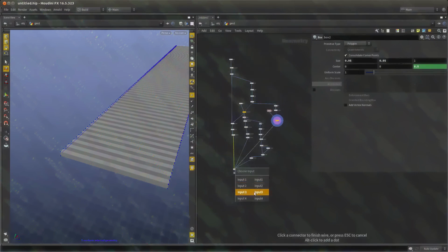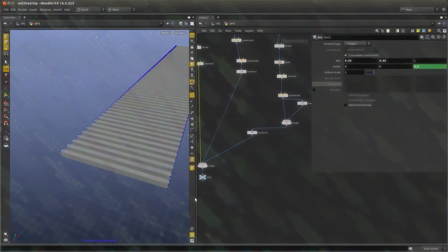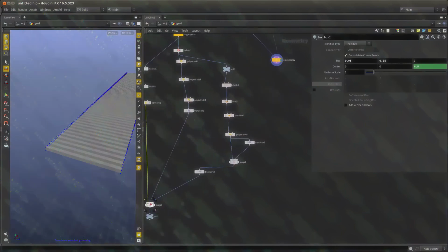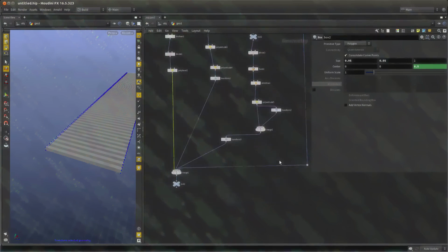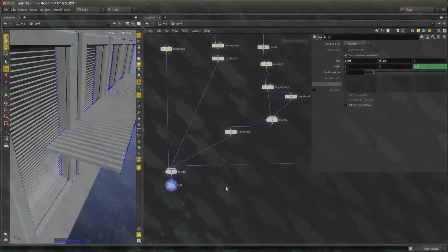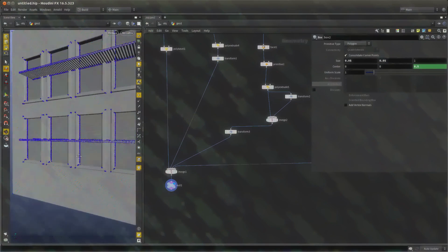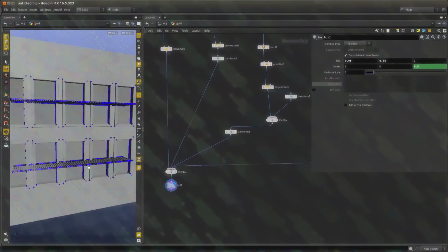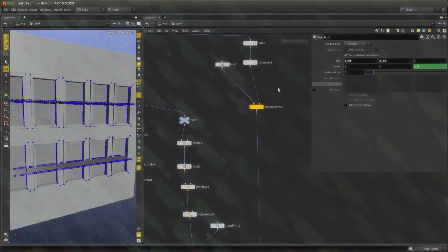And in Houdini 16, they introduced the dot concept. So I'm going to connect this wire. You can see it's crossing everything. I don't want that. I can hold the Alt key and drag, and it will create a dot. And this makes it easier to view the graph. Cool. So now we have lines in there, and we just have to transform them.